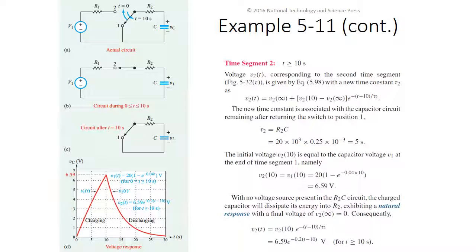And that discharge is going to immediately try to go down, start dropping voltage, because the capacitor is going to essentially be spending its energy going through that resistor and being discharged by the resistor. And eventually at 30 seconds, you're going to get almost back down to 0. And you can see at different times along the way what your voltage is going to be. So at 10 seconds, that's where you're going to have your max. And that makes sense, because 10 seconds is how much time we've let that charge up. So we've never fully charged it, so that's the highest it's ever going to be before we start discharging it immediately. And that's why you get that sharp peak there.